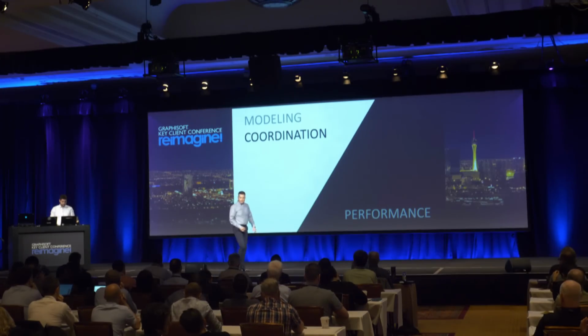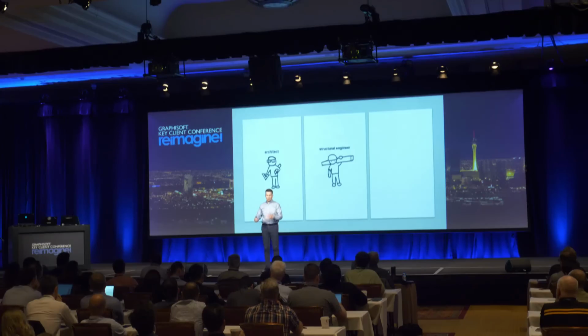Thank you, Ákos. So let's continue with another mission critical core functional area for BIM, which is coordination, bringing together the work of larger teams inside architecture. So how an architecture team coordinates their work. They have a project origin, obviously, in the BIM database, and they organize their work around stories. Once the structural engineer comes into the picture, obviously the global origin still works, but with the structural engineer, you speak along the lines of a structural grid.